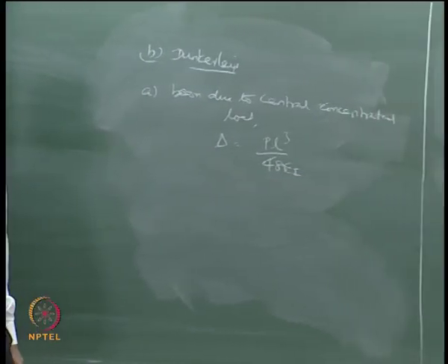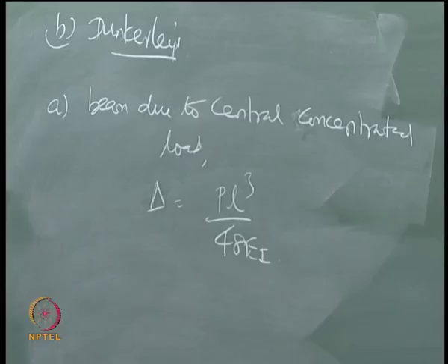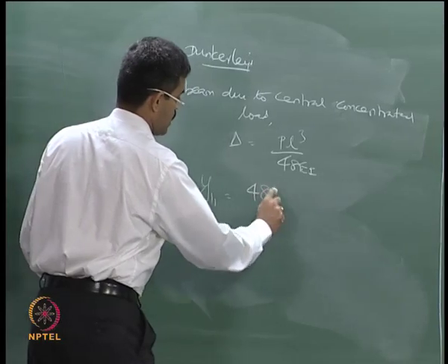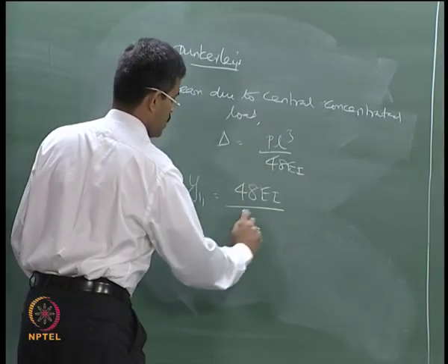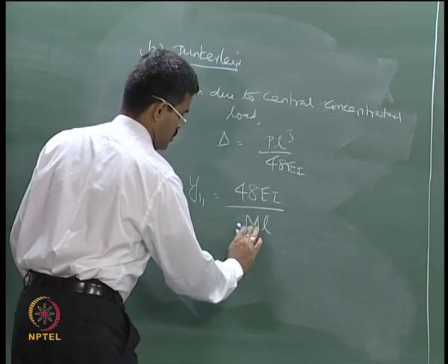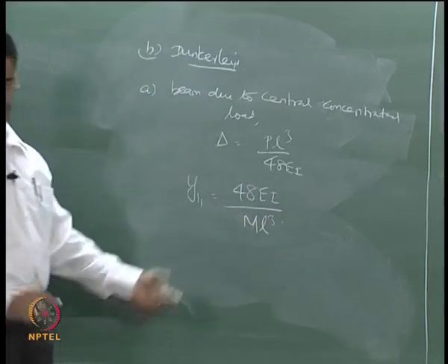So, I must apply unit force, get the deflection. So, I am interested in finding out Y11, that is the influence coefficient, which will be L cube by 48 EI. Instead of P, I am using ML, capital M.